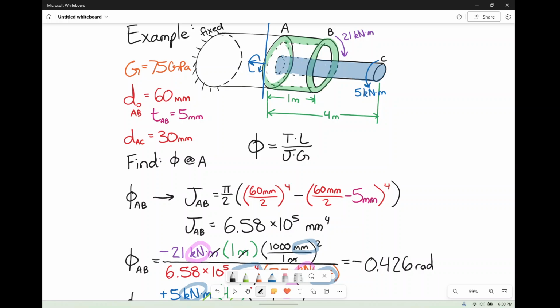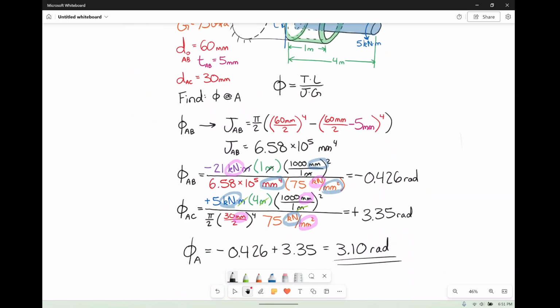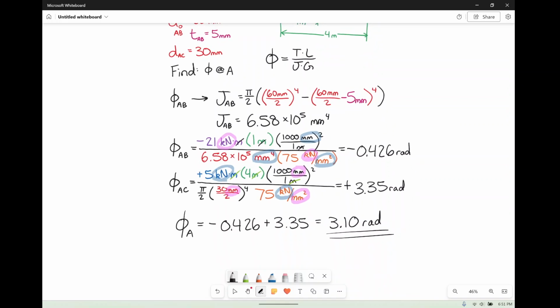So again, when you're looking at angle of twist, definitely do take into account the actual length of the member, not just how much further it is, especially when you have this weird little situation of a solid inside of a hollow. So hopefully you find angle of twist not too bad, because it's not really too terrible.